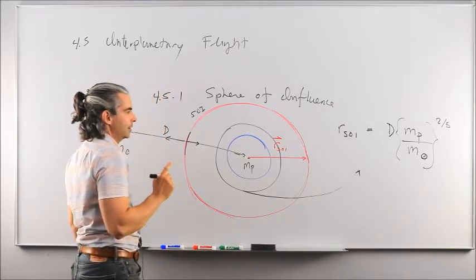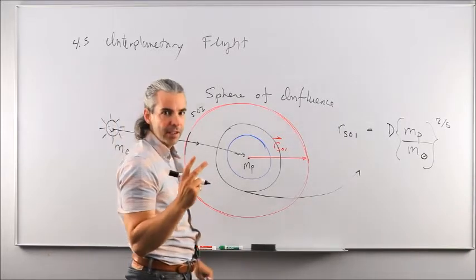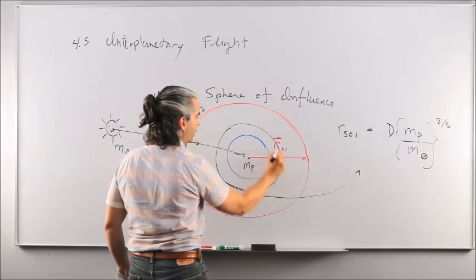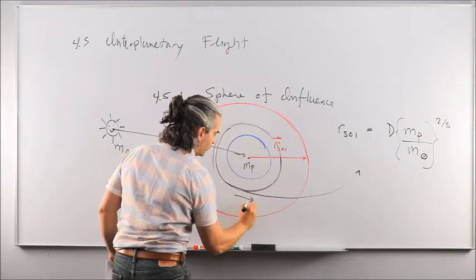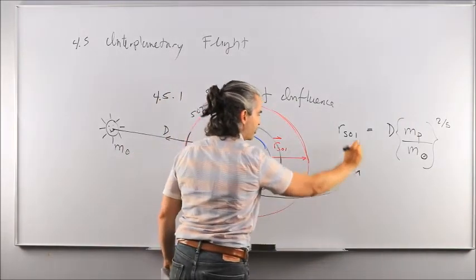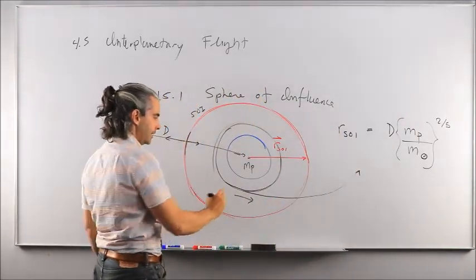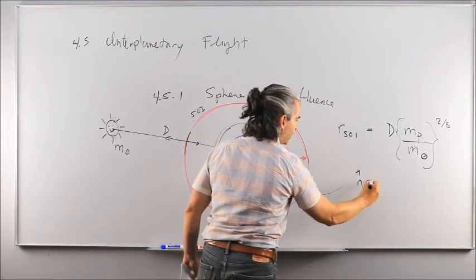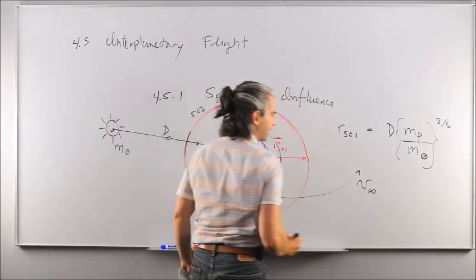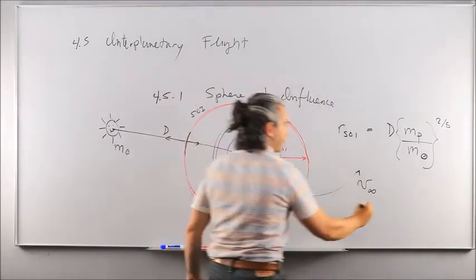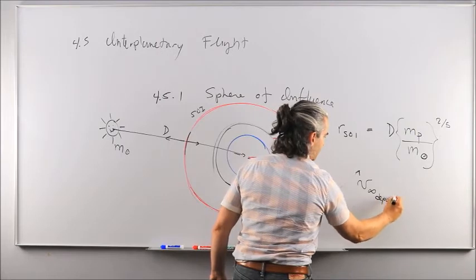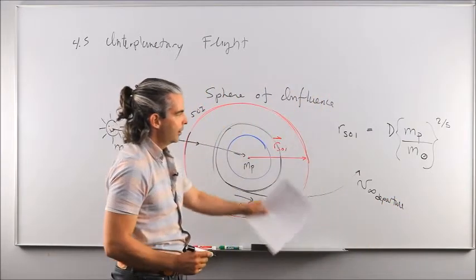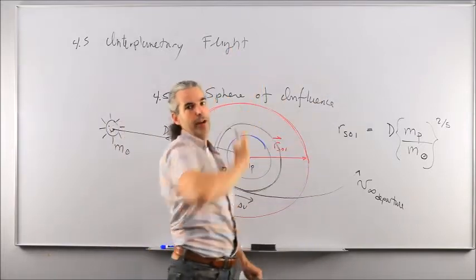So for an interplanetary flight, there are going to be 2 delta V maneuvers involved. One to go from the low Earth parking orbit to the hyperbolic departure trajectory, and this delta V maneuver is going to be sized accordingly to end up with a hyperbolic excess velocity, V infinity departure, which is great enough to reach planet 2 by freely coasting.